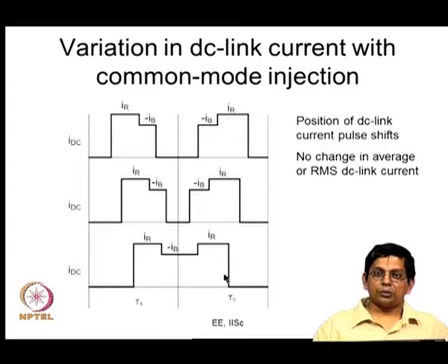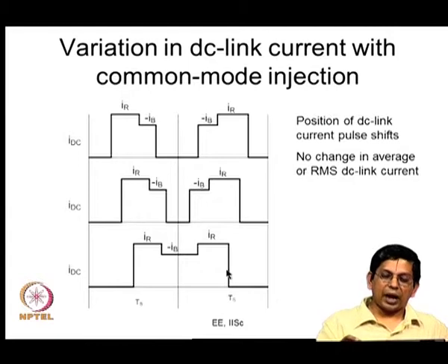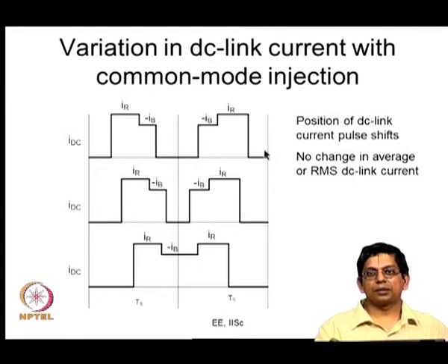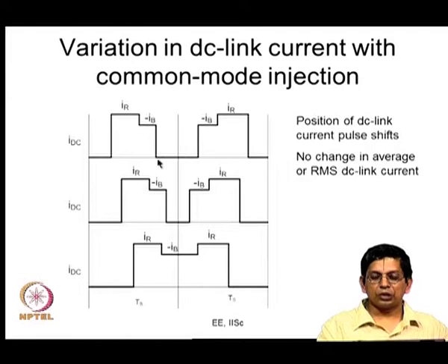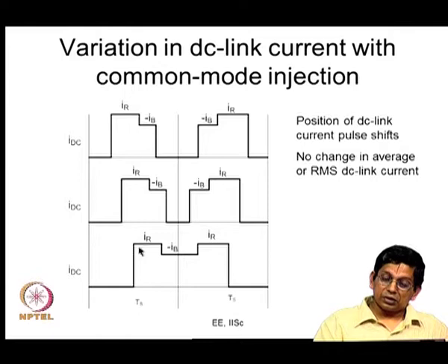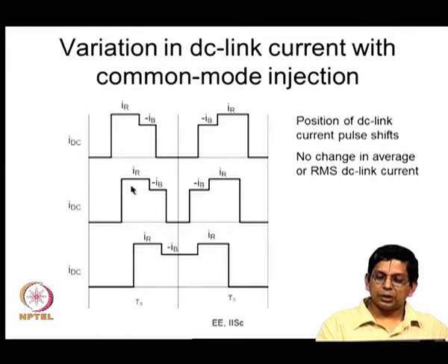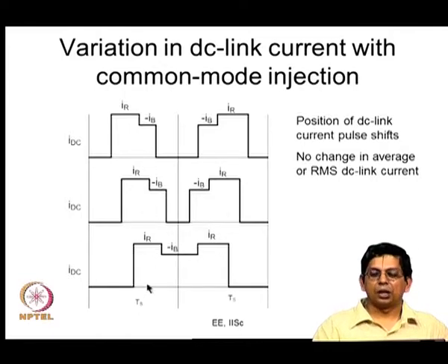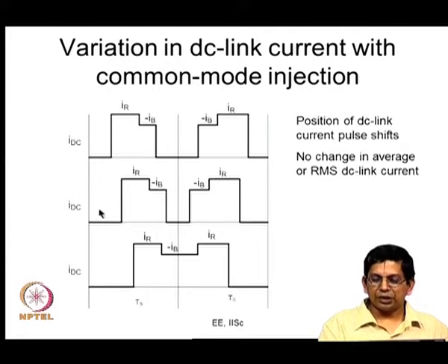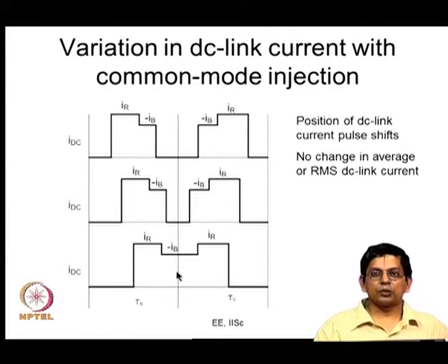So, in continuous PWM schemes such as conventional space vector PWM, if you look at the DC link current, you can actually say what the switching frequency is from that. This region from 0 to 0, because it is going through 0, is one half of a switching cycle, one subcycle. So, this is actually one complete switching cycle, alright. Now, this happens like this, so it goes around. So, what is the difference? The pulse position shifts, but does the average value of IDC over the subcycle change? No. Whatever is the average value here, the same is the average value here also, and the same here as well.